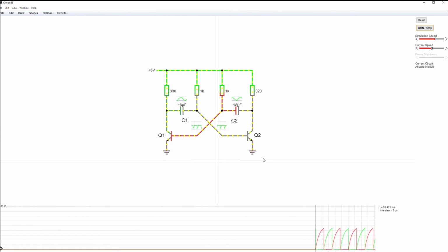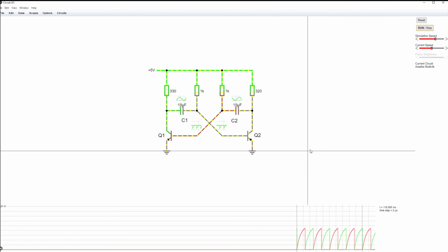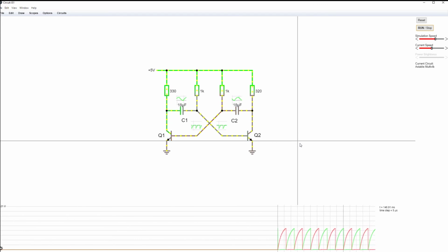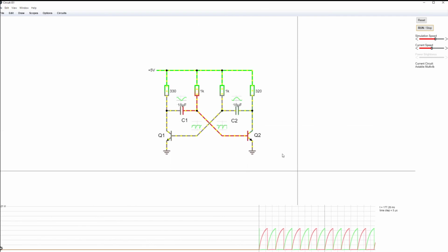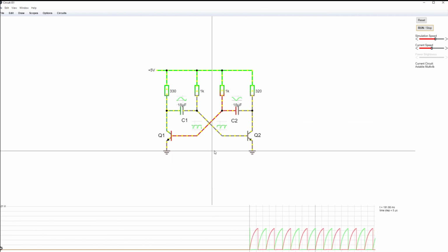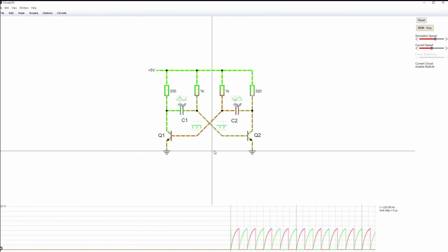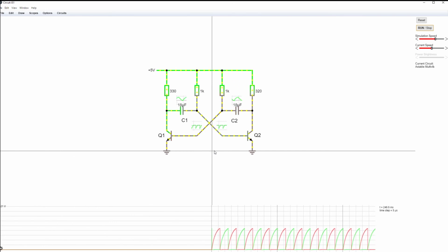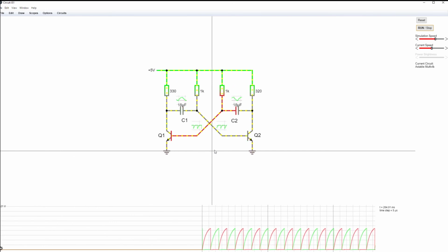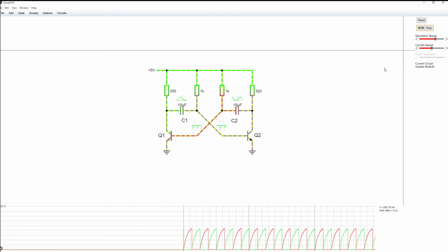This is used in a variety of simple circuits, because we can see here it makes a very simple clock mechanism, or we already said a flashing mechanism, but you can switch from one to the other. So you can switch from Q1 to Q2, Q1, Q2, and that can generate a wave. If you plug it up to a speaker, you can make a positive and negative voltage, so you can get a sound. So it's a very simple way that was used in early electronics to get some sort of a cycle happening with power or LED lights or some other source.